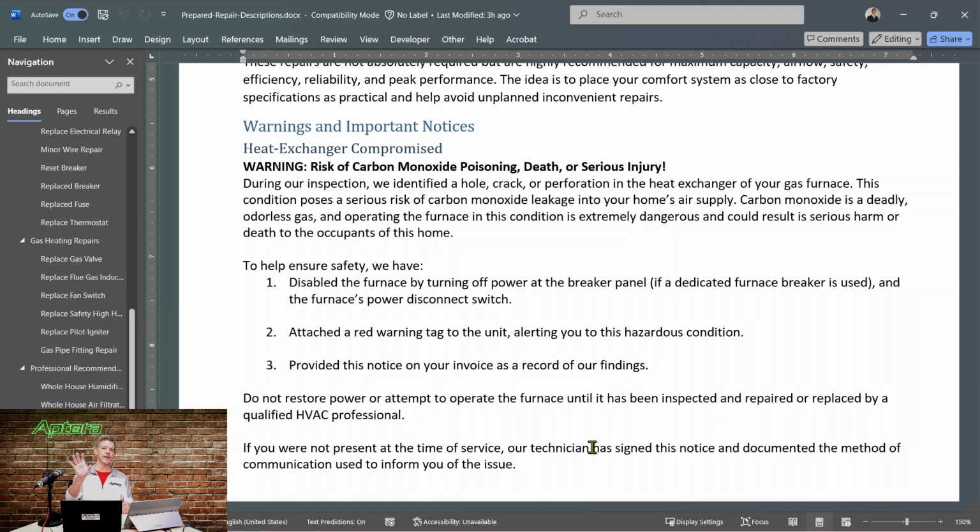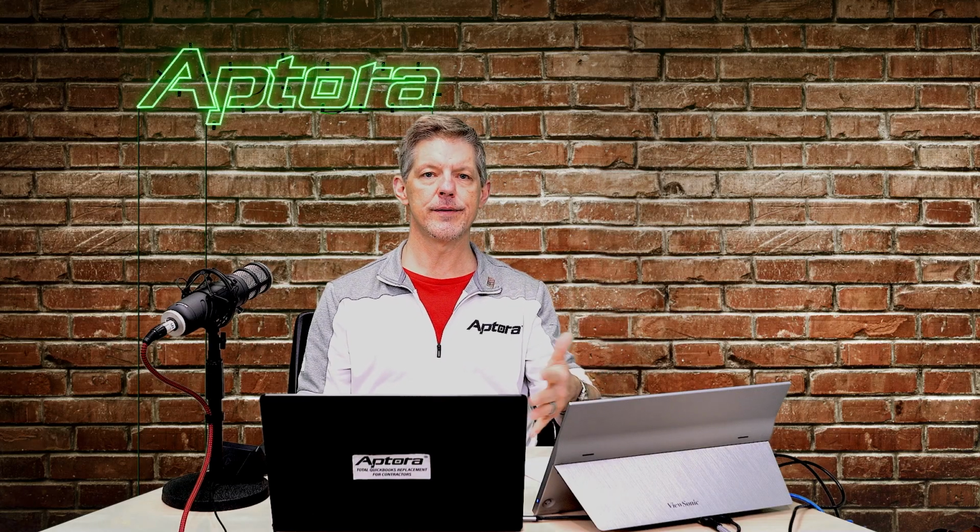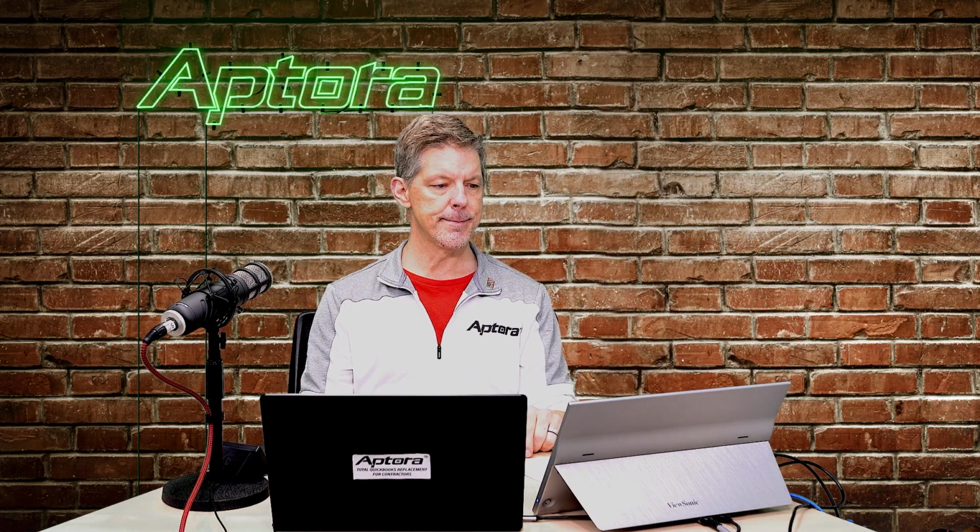If it's dedicated, the SOP would say, if it's a dedicated breaker, turn it off. If there's a switch, and there should be on the side, then flip it off. Maybe take a piece of red electrical tape and put the tape over the switch. Maybe put the tape over the breaker. If you think that's a good idea, then you would mention it during training, but you'd also put it in the SOP. The SOP would mention that.